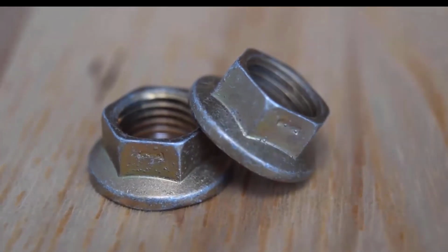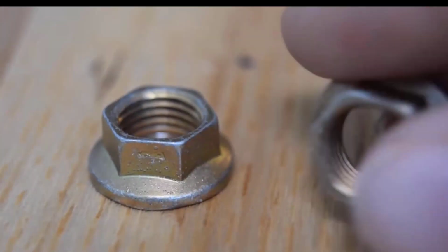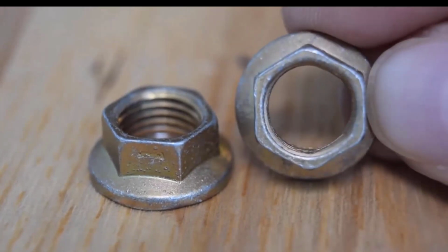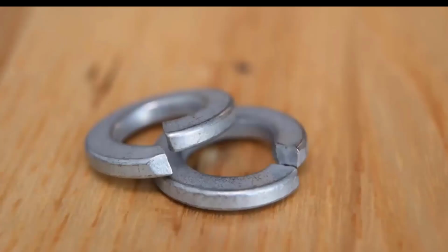These come in a few different styles, but in all cases, the threads are specifically made slightly out of round so that they tightly grip the screw threads. You may have seen these bent lock washers at the hardware store. They don't do anything and really have no place in engineering applications.